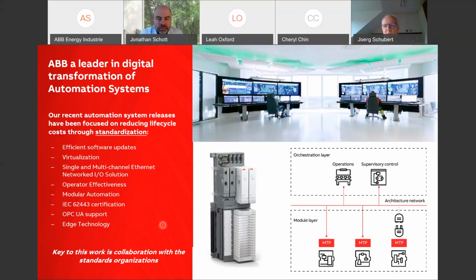And as we are moving to network-centric, and you talk about cybersecurity, one can question how the proprietary fieldbuses like Profinet, Ethernet IP and Modbus TCP will address this in the future. For us, the path forward clearly is to utilize OPC UA on as many of these layers as possible, because it has built-in cybersecurity and supports peer-to-peer communication and client-server communication.